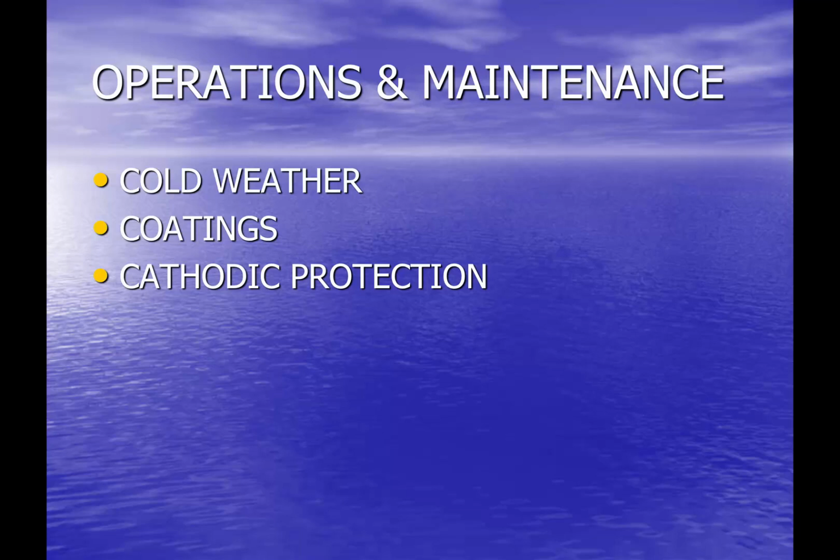One of the reasons some agencies might go to cathodic protection in addition to a coating, which typically you're going to have a coating no matter what. Anytime you have a coating, if you've got any kind of pinhole or what they call a holiday, then that's where the corrosion is going to go off relatively quickly because it's not protected. So cathodic protection might be the backup to it. We are not doing that. We're relying primarily on our coatings.